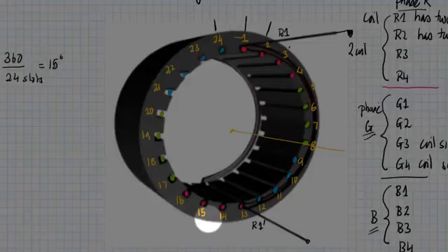Now we said that the location where the maximum value of the MMF of the R phase occurs lies exactly in the middle of the phase of R. That is, you have the phase of R spread out here and here, and the maximum value of the MMF occurs exactly in between. So that's not exactly here as we have drawn it, slightly shifted. So the middle will occur right in between slots 8 and 9. Now let me draw this with a red line so that we know that this is the axis of the R phase.